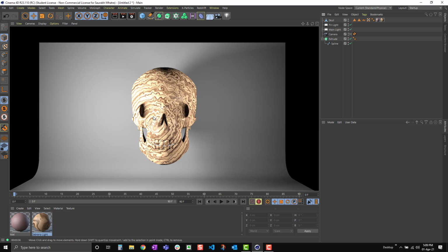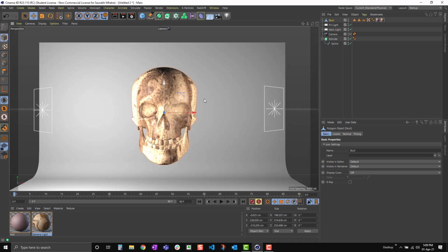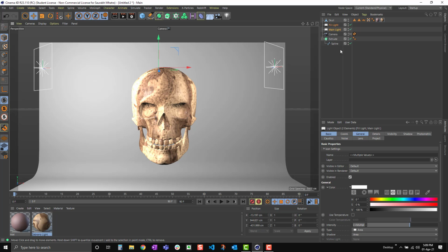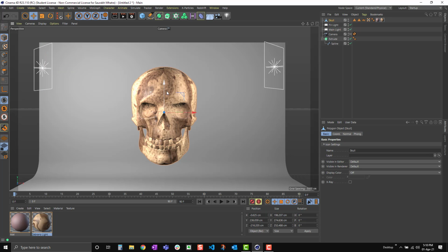Now you can see the render is not that great. We're not getting great shadows here because the light is probably too direct. I can do a few changes, maybe lifting up the lights, taking my main light on the left, because it has a lot of highlight. I'm going to reduce its intensity to maybe 85. Let's see, re-render.